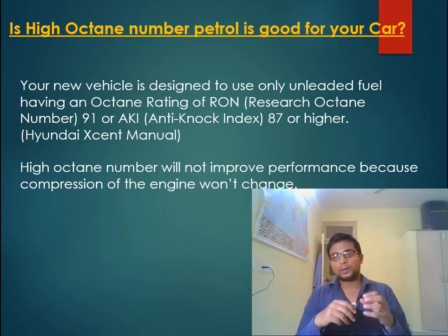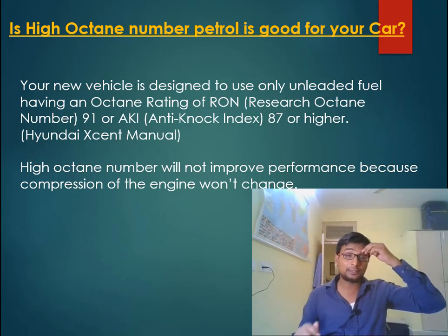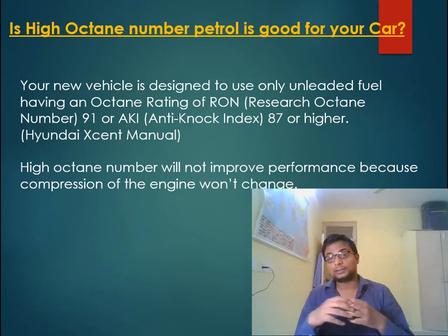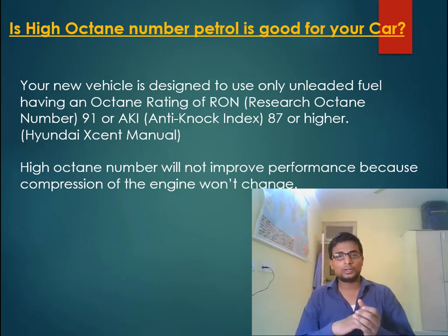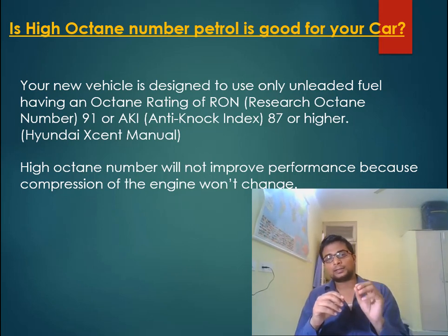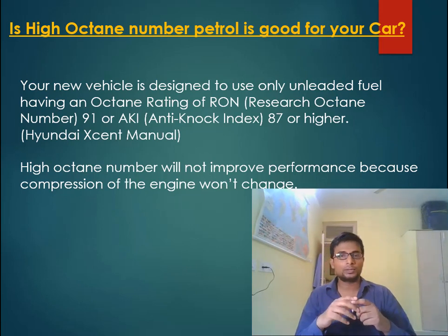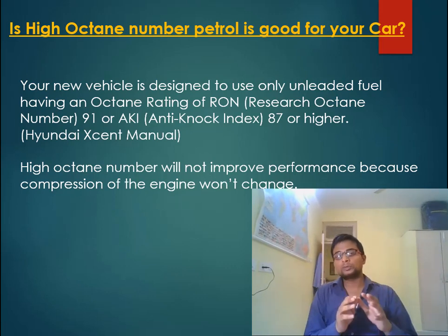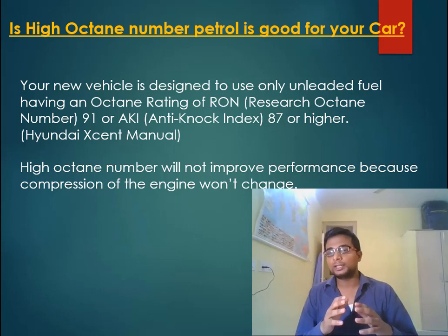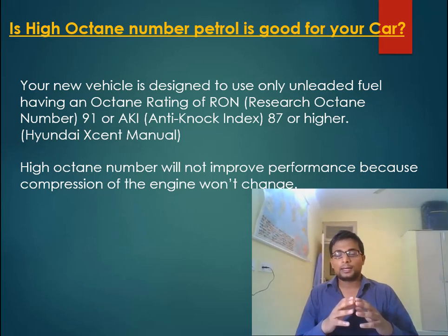But some very high speed cars, very costly cars, may be designed for a high compression ratio. In that car, if you are using say 91 octane number, then that car may knock, and that may damage your car. So you should check your car manual for what the octane number of your fuel should be.